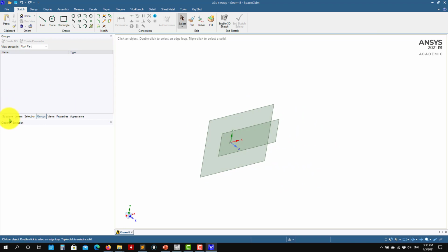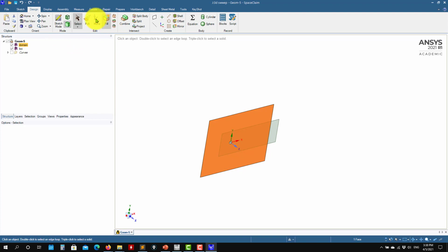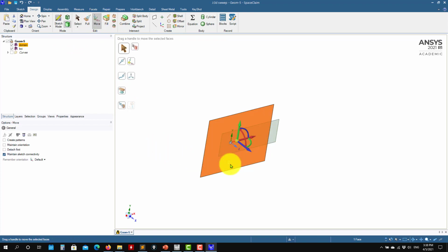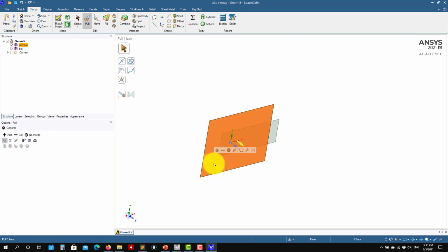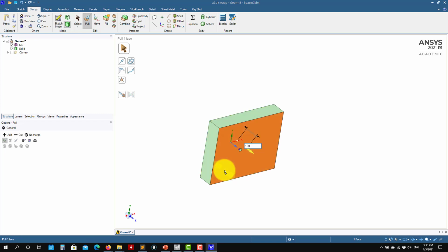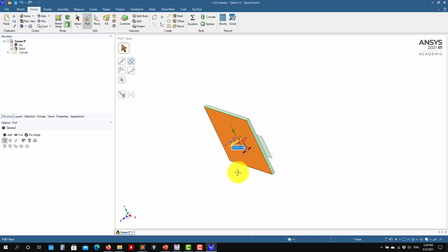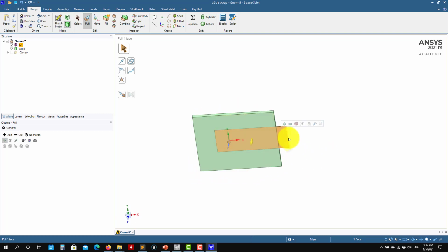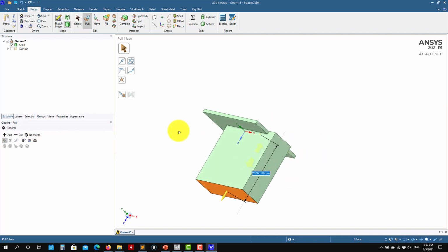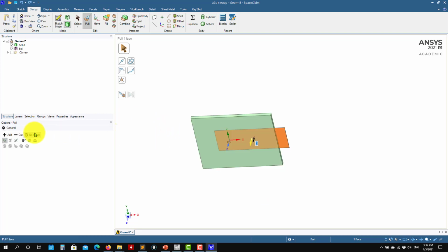So first, select this one. Remember, you have the universal pull tool here, and you just pull it up. Okay, I chose move, the wrong one. So pull it, 1000, 1 meter. You have that universal pull here, and then you have the other one here. You do the same, but before pulling, disable the merge, because if you pull here, it will automatically do a merge. So undo, and remember, no merge. It's not going to do the merge there.